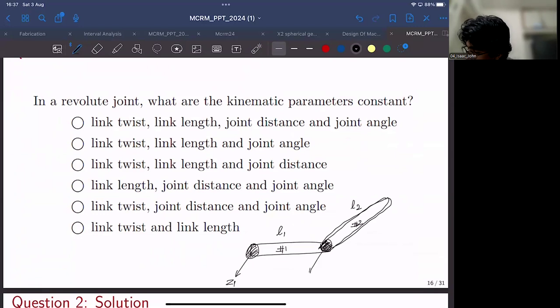This is Z2. And the relative orientation between link 2 and link 1, I label this as theta 2. Right? So I'll label this as Z1. This is Z2. This would be X1, which is along the common normal between Z2 and Z1. This is X2.